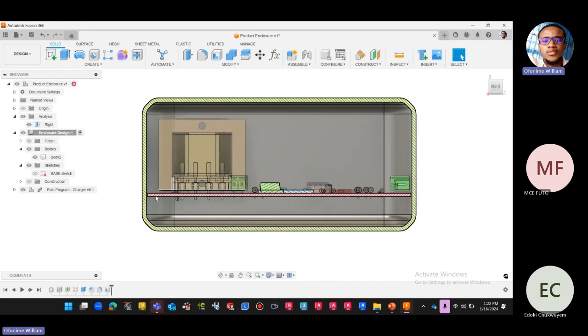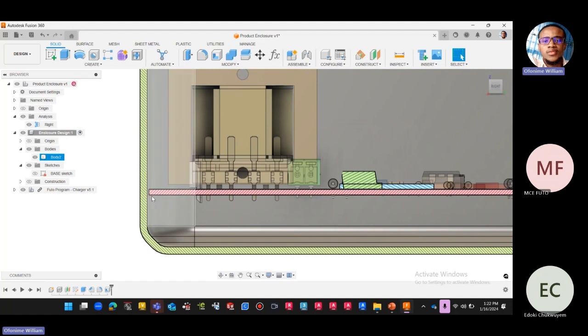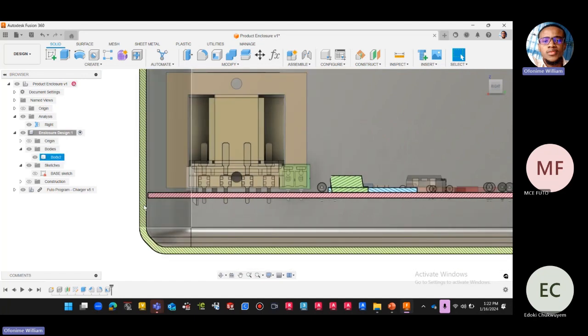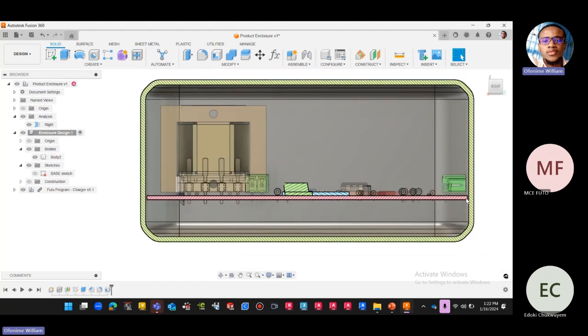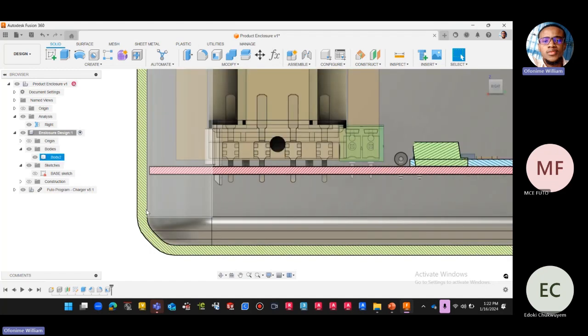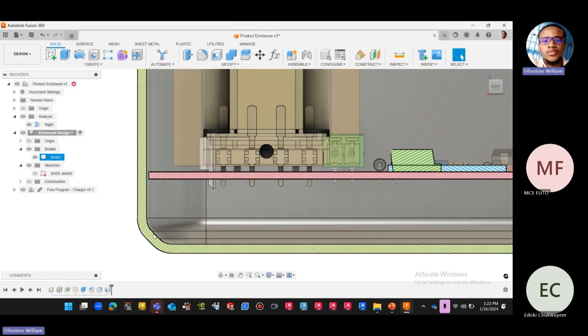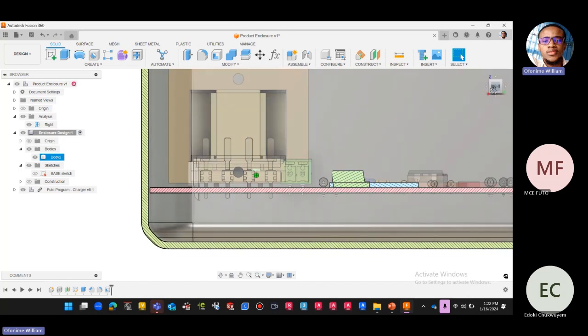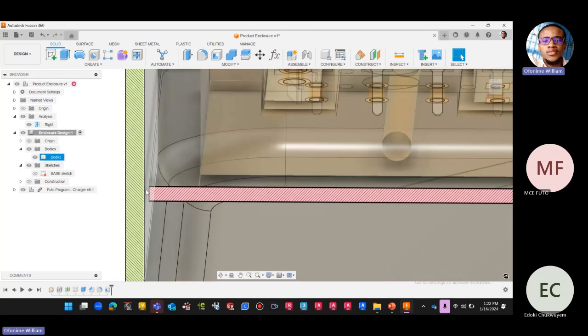So that one will become my inner wall, right? And the shelling now is happening outward. So it's still removing material and remaining a wall, but it's doing it in the negative direction. That's the outside direction. You understand? If you check this wall, it's still going to be whatever I set as my wall thickness, maybe 2 mm. So this wall will still be 2 mm, but respecting that I had kept a clearance here.